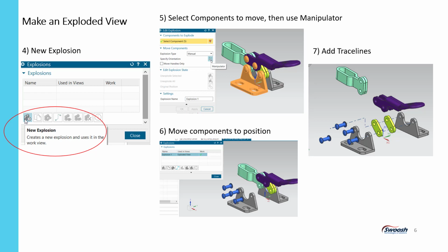Now, in the video, a couple things to note. When we switch to modeling, it happens pretty quick, so we'll point that out. But I'm going to make a mistake when building the video. When setting up the stagger in the components and moving them around, the two center ones you see, the purple arm and the greenish clamp, I didn't move them over far enough, so there isn't enough room to bring the trace lines through and get the jog like you see on the one rivet going through the two center arms.